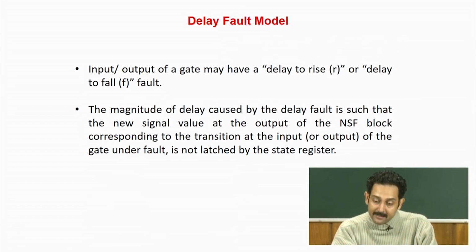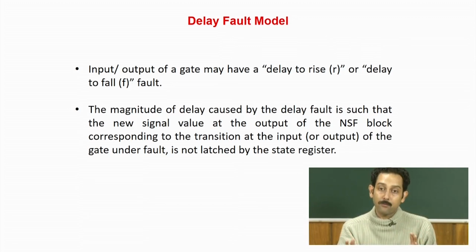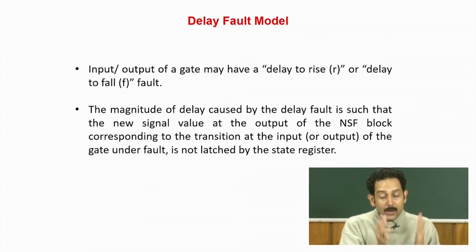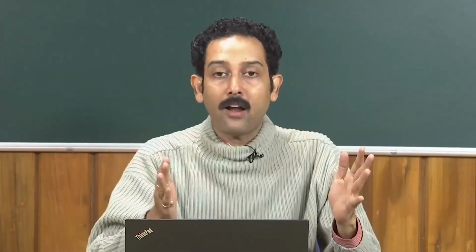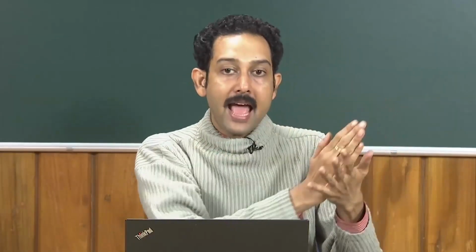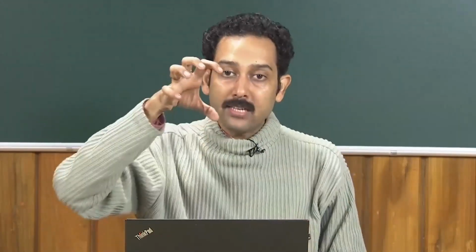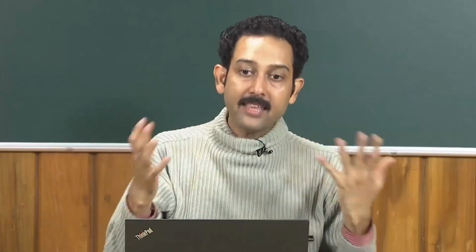But as we will see, delay fault generation is also complicated, and fault application requires a very high cost ATE, because here the patterns have to be applied at the gigahertz level. If you are going for a delay fault test, you apply some patterns and then the next pattern, and you should know that the AND gate is computing the results at the near accurate time. So obviously the test pattern has to be applied at a very fast rate, and the data has to be latched at a very fast rate, at the gigahertz level, which is typically the operating range of the circuit.